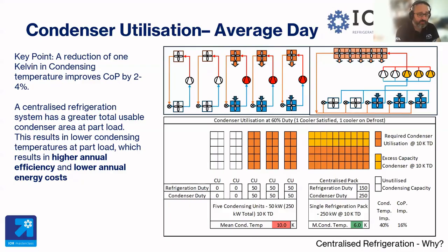And as we know, the power consumed by a fan is proportional to the cube of the change in fan speed. And then there's even a fourth consideration to make. With lower fan speeds, our face velocities onto the condenser are low, which means that we'll probably have, to one degree or another, a reduction in the intensity of fouling of that surface, resulting in less entrainment of debris onto the condenser face. So there's potentially a lot to be saved here just by having a bigger condenser all in circuit at one time.